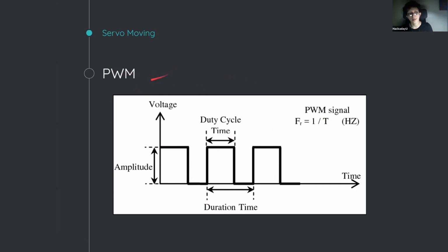What PWM means, it stands for pulse width modulation. That means that you're going to be sending a pulse, and this is the part that you're going to be modulating, right? You have a standard time, which is like the hertz that the device works with, and then you change the time the pulse is on, and that's going to mean something for the part that it is connected to. If the pulse is on half of the time, it's going to mean something. If it's full or if it's low, etc.